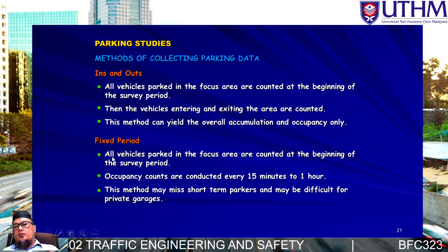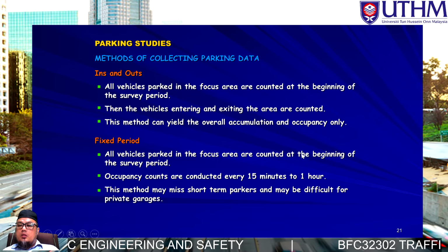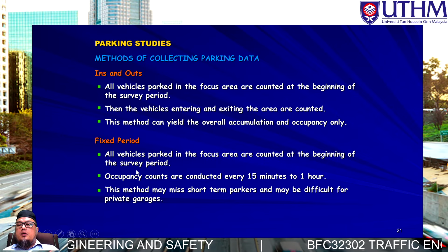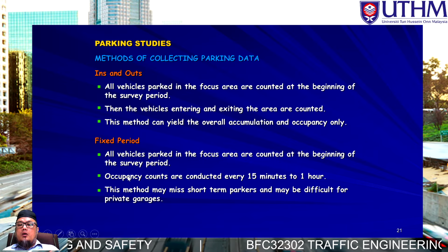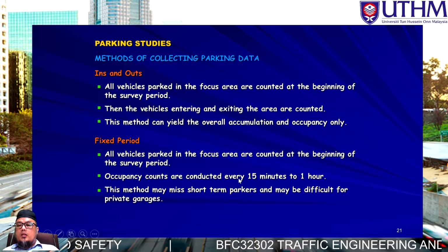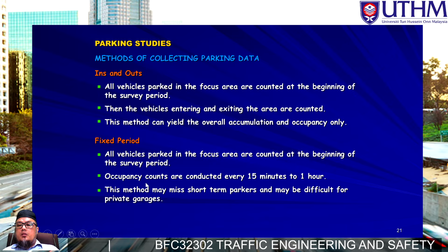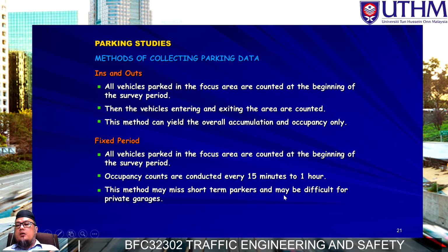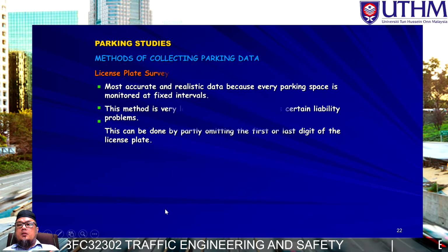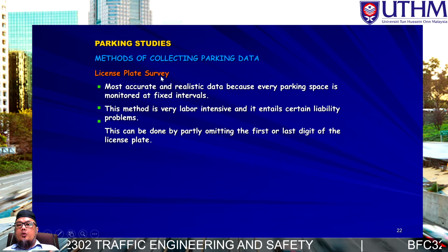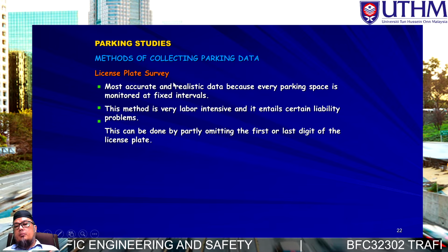Okay, fixed period. All vehicles parked are counted at the beginning of the survey period. Occupancy counts are conducted every 15 minutes or within 1 hour. This method may miss short-term parkers and may be difficult for private garages. Okay, this next one is quite popular and I think quite a suitable method.